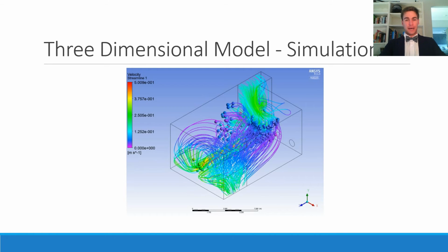The streamlined path plot again provides further details on the expected hydrodynamic performance of the anoxic zone. The simulation shows that above the path of the A-recycle pump and through the middle zone, the velocity is less than desired. The streamlined path plot also highlights regions of the zone that may be subject to settlement, and therefore where undesirable biological conditions could occur. Furthermore, the flow seems to move directly towards the larger outlet, which suggests that short-circuiting is occurring.